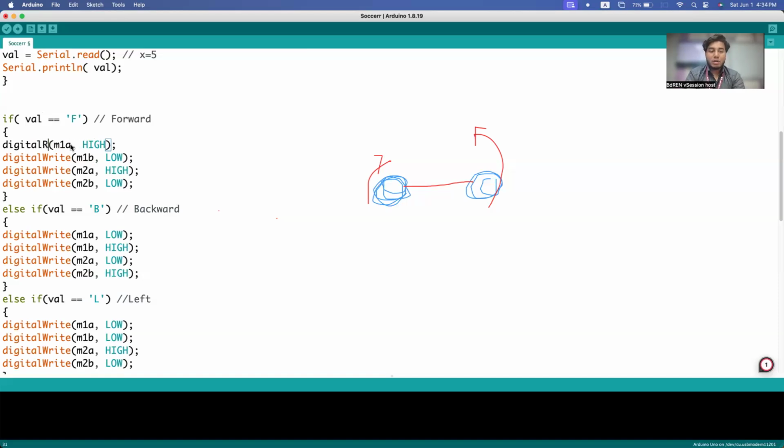Okay. So as you're working with the motor, you have to write. You have to execute some value. You have to rotate the motor. So it is the output function. The output is what you write. And if you scan something, if you take the input, then you have to write digitalRead. And the same goes if you're going to work with the analog side: there will be analogWrite as well. That will be okay.